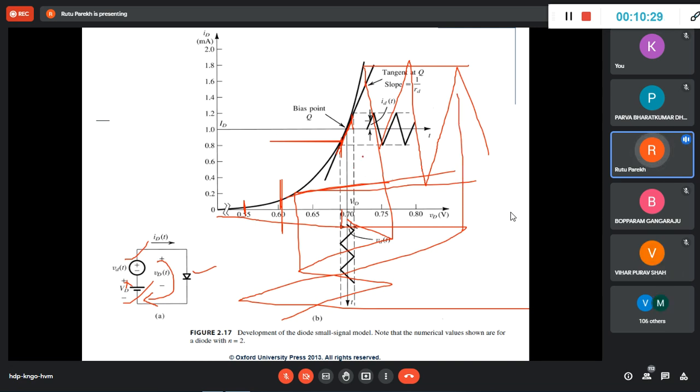So your signal is distorted. As I explained last time, your signal is traveling in the form of current. And if your current is not proportional to your input signal, then at the output you get something else. For example, I'm speaking now, and the amplifier which is amplifying the signal is linear. So for low amplitude or high amplitude, it will amplify with the same multiplication factor, the amplification factor. But if it is behaving non-linearly, then my tone will not be equal, it will vary. So it has to be linear.